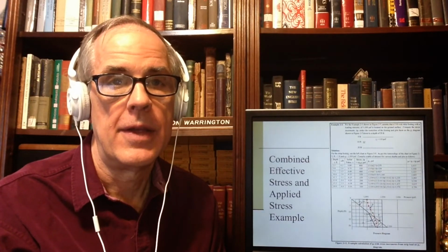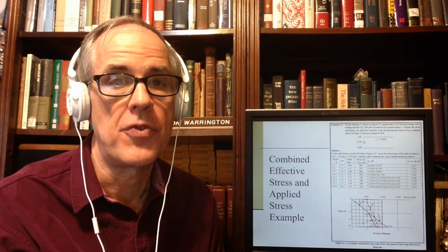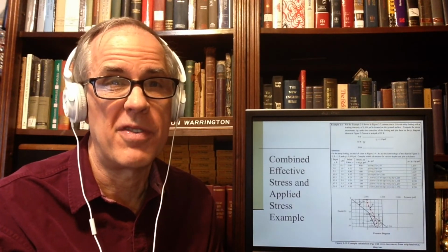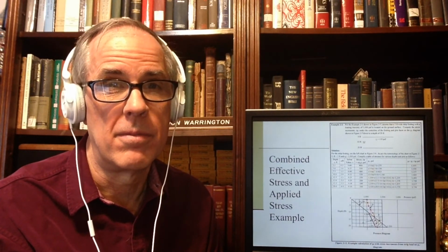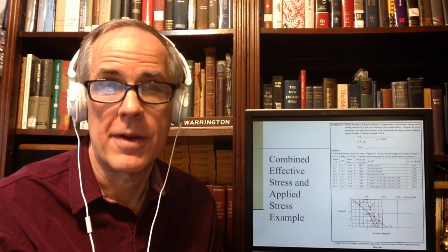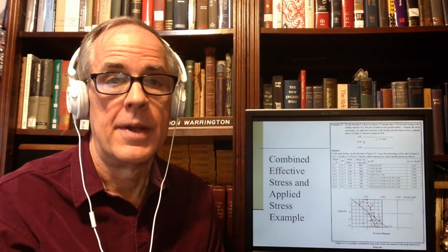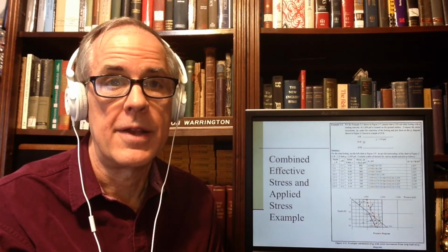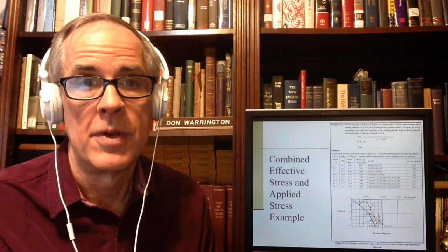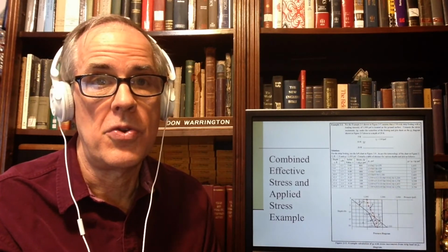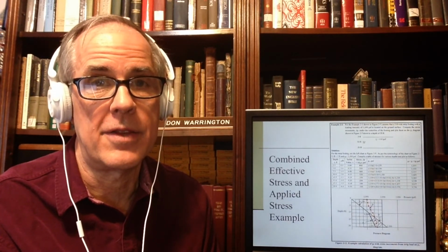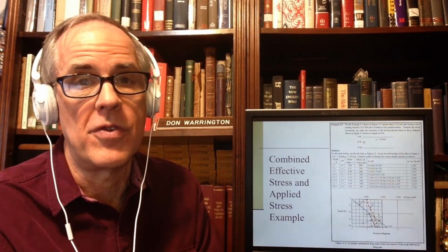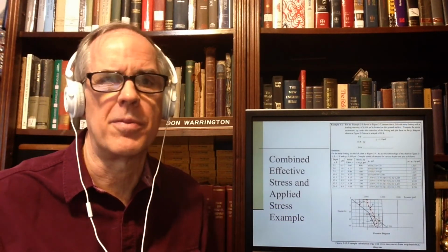However, and this is what we're going to find out in consolidation, if you've got a soft layer down there, I mean, uniform stratigraphies are not common and should not be expected, and it's likely to compress, your interest in what's going on down there is a lot greater than if you know you've got uniform or reasonably uniform stratigraphy.